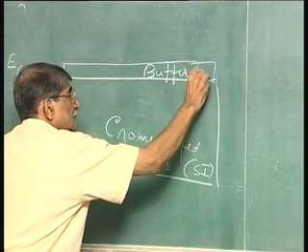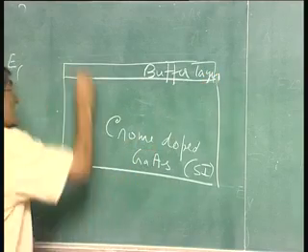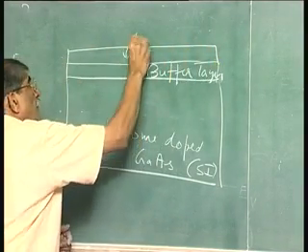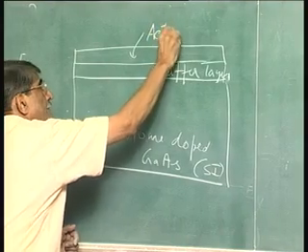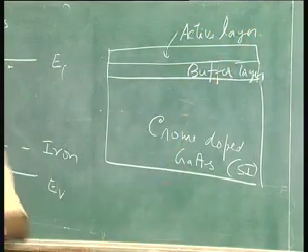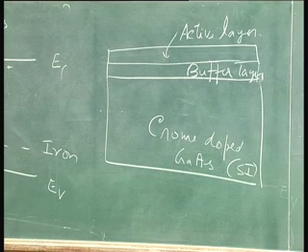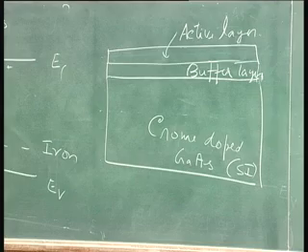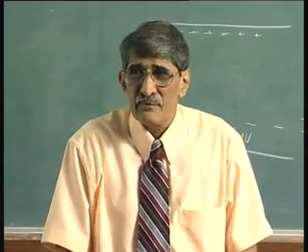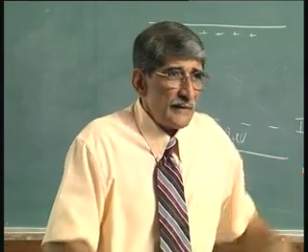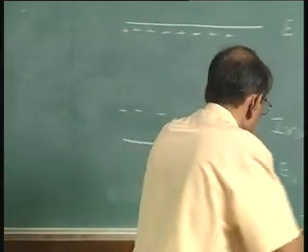Buffer layer. On the top of that, you grow your active layer. That is what they were doing. So, in case when you see in the publications, if you see a buffer layer put, that is mainly because it is a chromium doped. When you use semi insulating substrate where you have not added deliberate impurities like chromium, you do not need buffer layers. Straight you can grow other layers. Let us go back into this now.